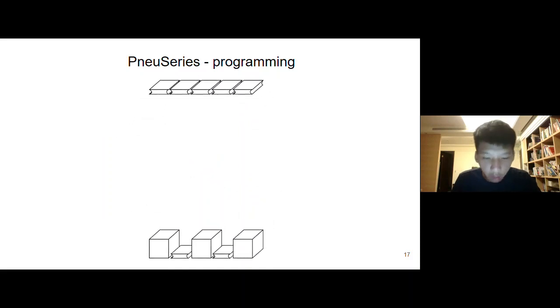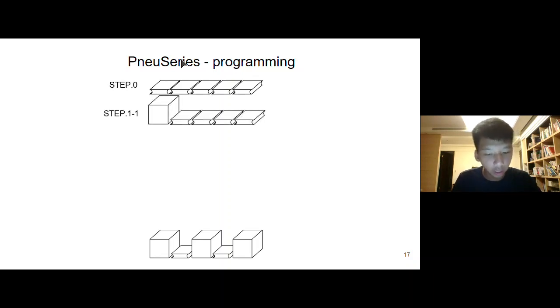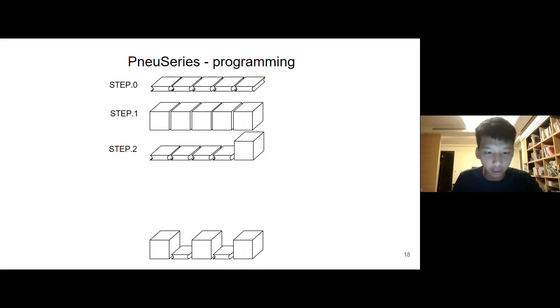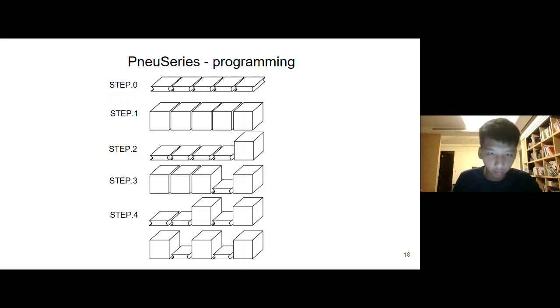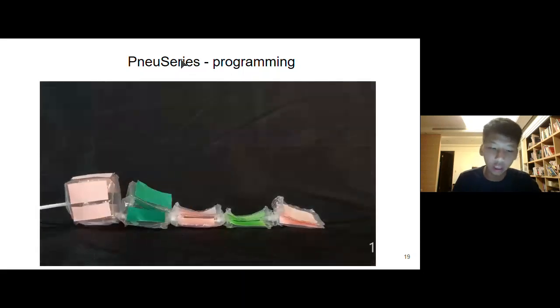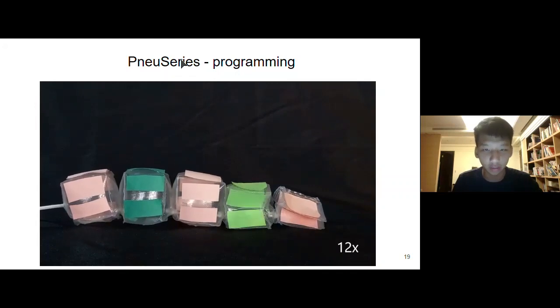To reach the target shape, we divide and conquer to make the rightmost inflatable match the target shape. That is, here the system keeps pumping in until the rightmost is inflated. As the rightmost is inflated, the system then considers the second rightmost and so on. So we inflate the inflatables one by one until all inflatables reach the target state. Finally, that's what we see in the video from the beginning.